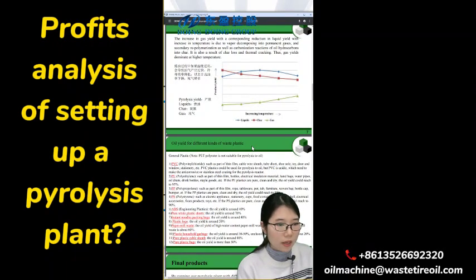But what I need to say, PVC and PET are not suitable for pyrolysis oil, because PET does not contain oil. If you process PET, maybe you cannot get oil, then there's no profit to do this project. And if you process PVC, the PVC maybe will produce toxic gas.